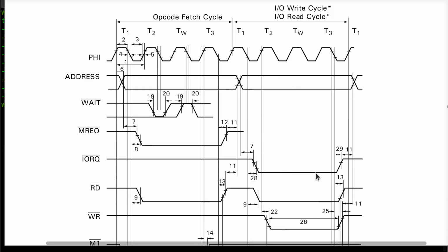When these go low and the clock is going around, phi is the master clock at the CPU, and it provides that back to the FPGA. I've got that as an input in my FPGA design. So I've got this clock, and I'm going to use this as the clock for my logic that's going to come up with a variation of this signal here that's synchronized to phi, and it will go active for one clock period. All right?